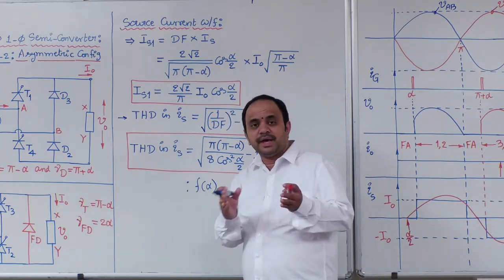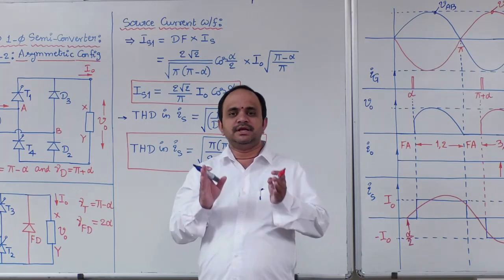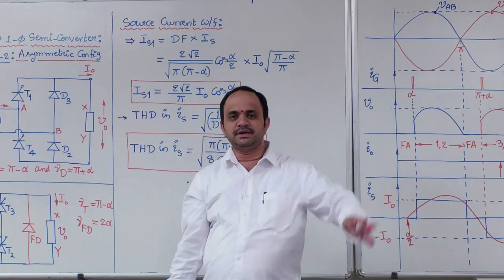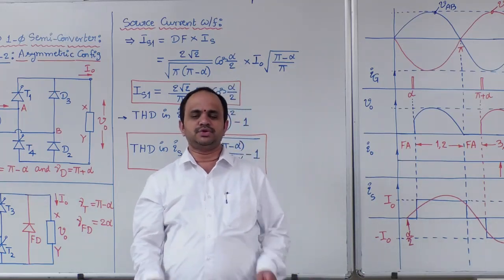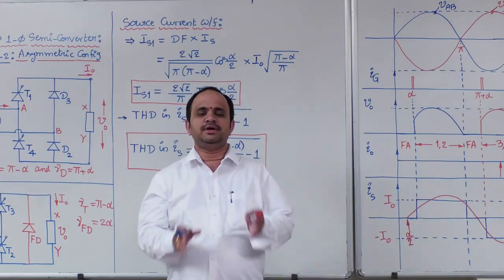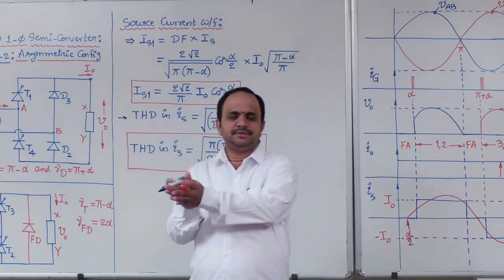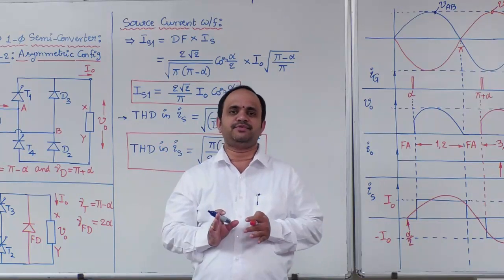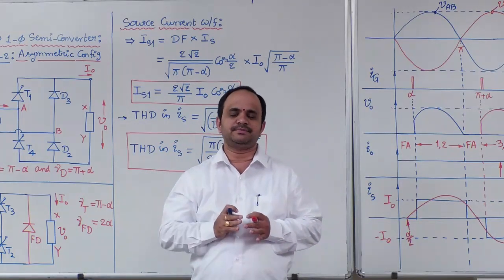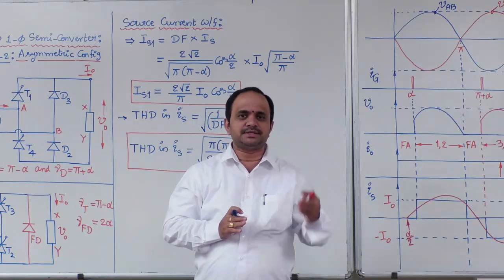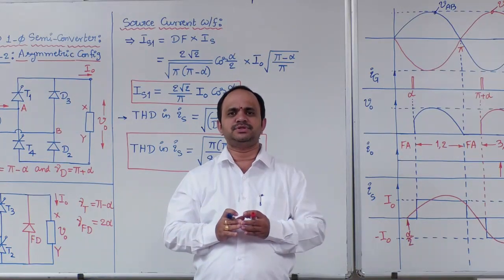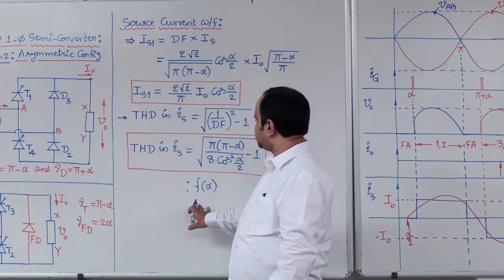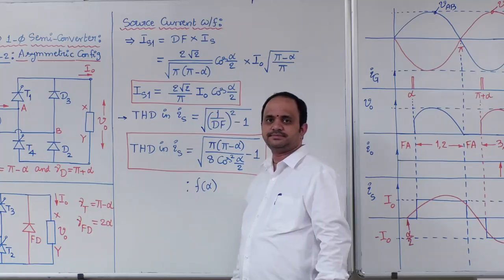Now, in comparing the power factor, single phase semi converter has better power factor in comparison with the single phase full converter. So if you conclude at a high level, full converter single phase, semi converter single phase, power factor wise semi converter has better performance because of the freewheeling action. Motoring and braking wise full converter has better performance, so you can select depending on the application. Okay, so this is about conclusions on source current.